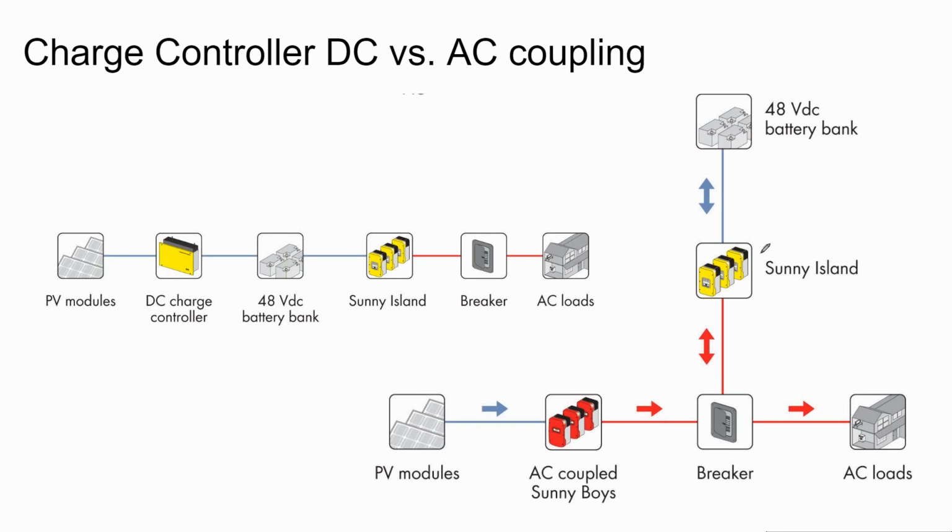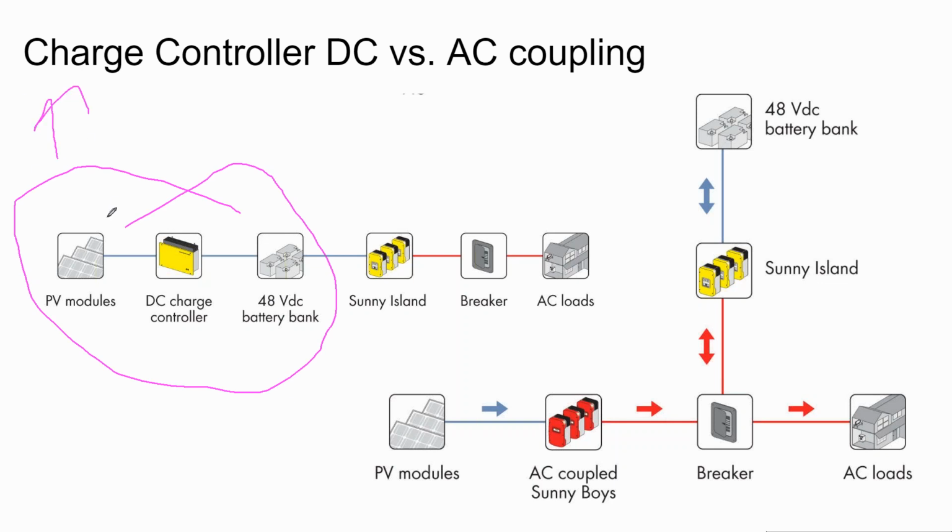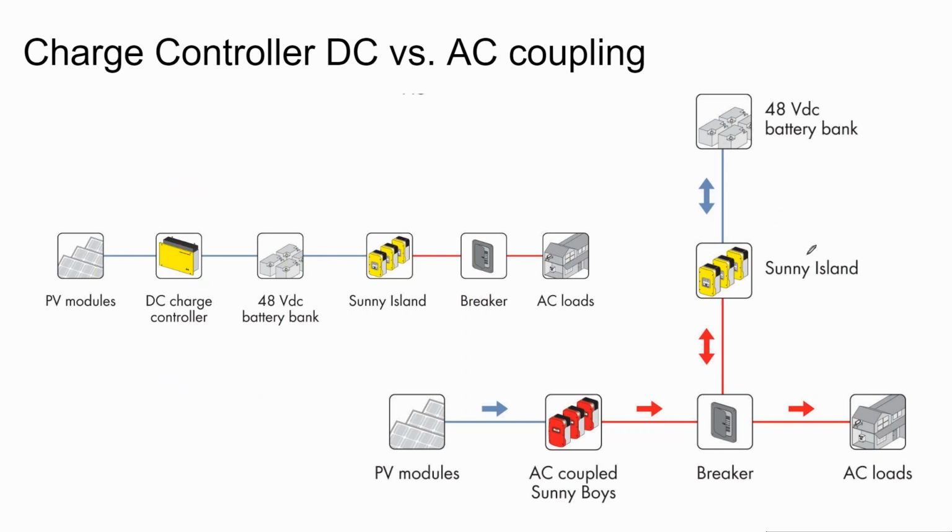Generators kind of have a similar issue where there's a battery inside the generator to power that electric start button on the generator. And if that battery drains, the electric start won't work, and you might have to hand crank it. So this is not just a solar issue, but you'll see some discussion of, in AC coupling, the system won't be able to black start. Whereas in DC coupling, you don't have that issue. As soon as the sun comes up, the batteries start to recharge. And so maybe there are a few more technical merits of DC coupling.